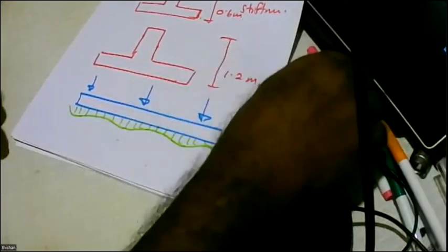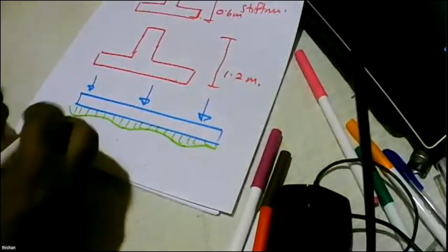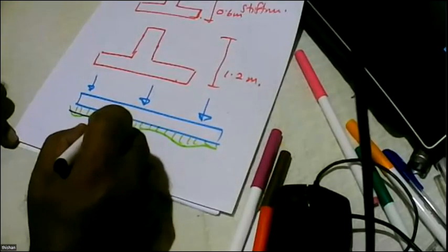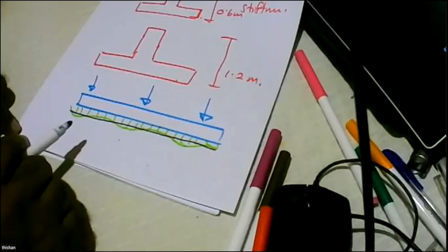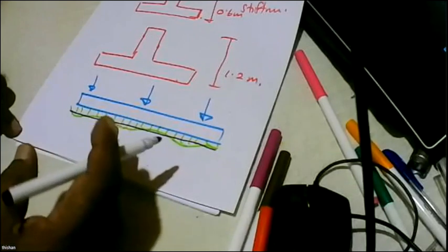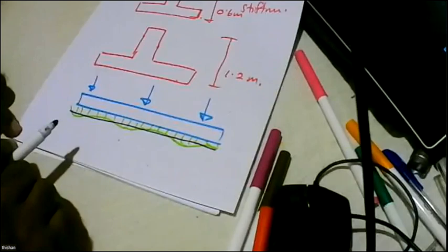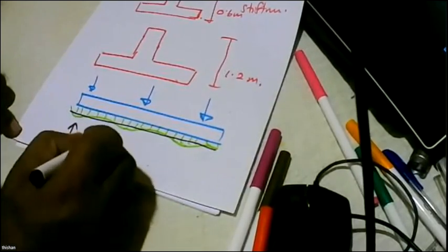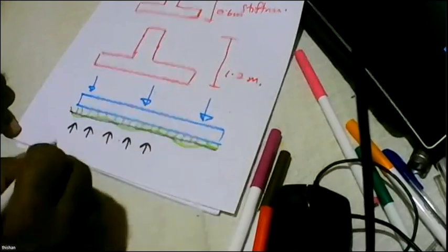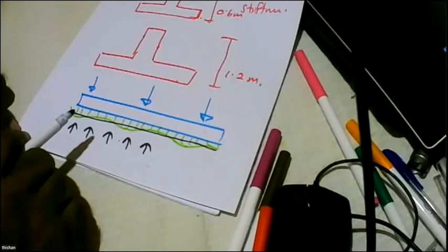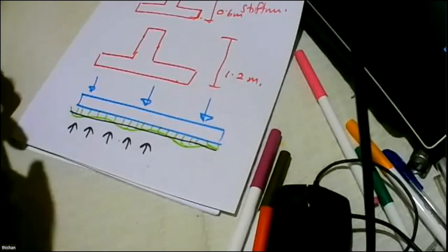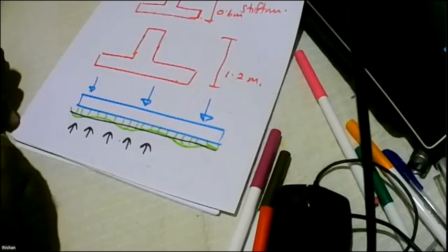But if the foundation is firm, we might find that it flattens. It flattens. So by allocating different sizes for this inverted T-beam, the stiffness will change. We might be able to see how the reactions vary, and reactions will give an idea about the load on the soil. And if we like to see that the load on the soil is fairly well distributed, then we will need a stiffer foundation.